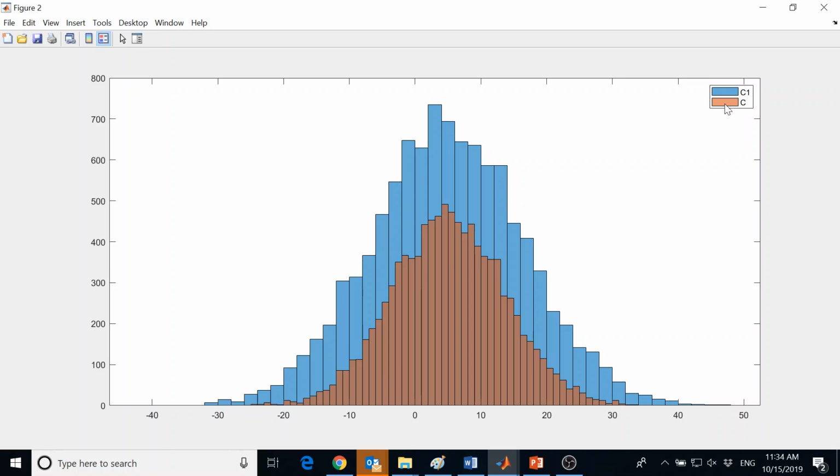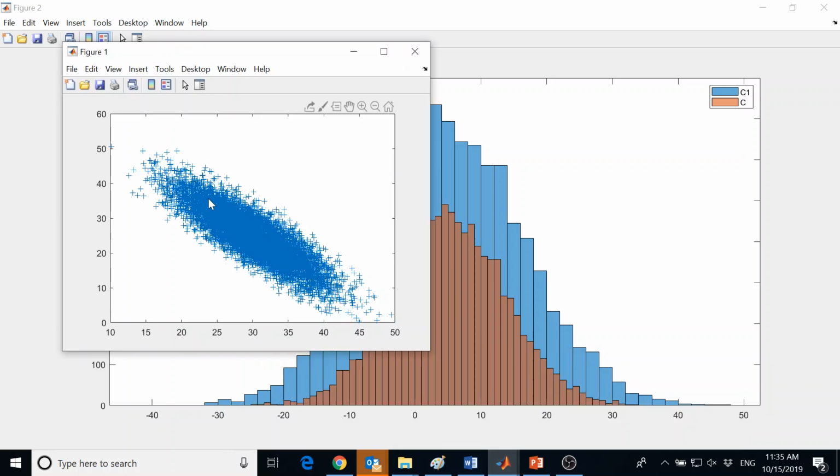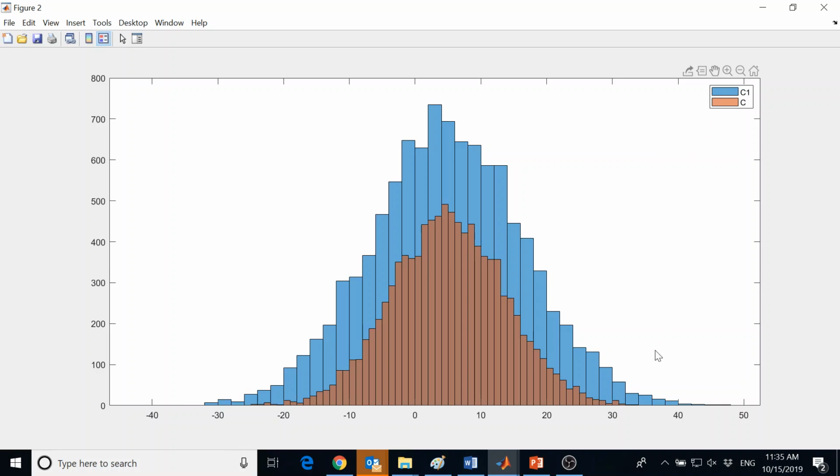So remember, C is when you don't consider any correlation. If you want to design for the 90th percentile, you're going to go here. It doesn't look like much because the scale changed, but you're still going to go here, about 25 feet. You're going to design for that. But if you consider they are negatively correlated, like they are intentionally trying to make their differences bigger, then your simulated 90th percentile will be around 30. So that will make a direct impact on your design decisions.